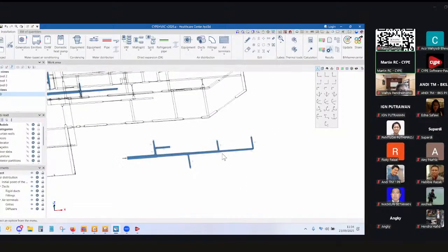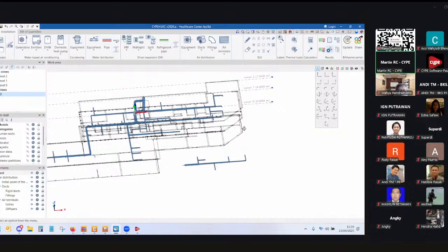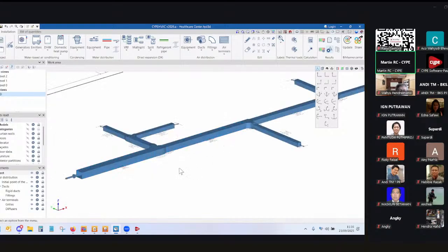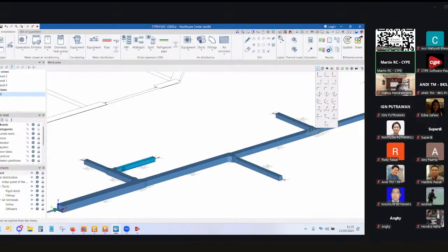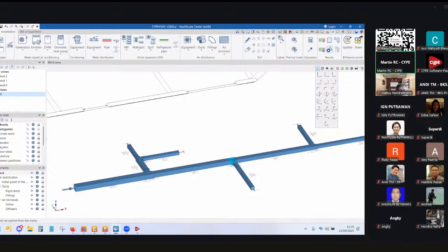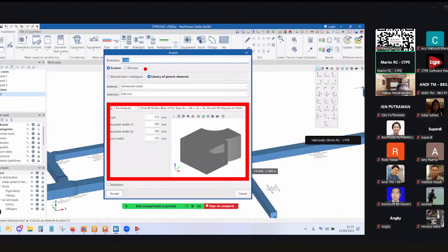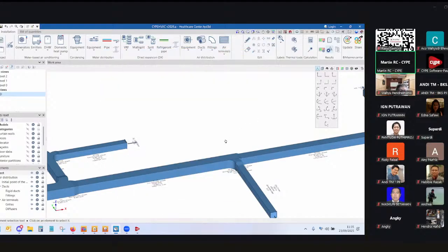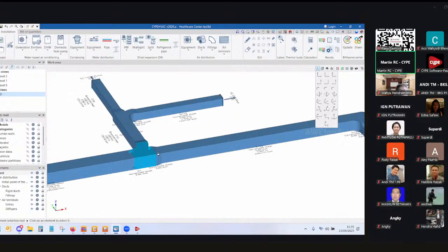If it's blue, it means I have properly connected all the elements in the installation. And see that we have an output where I have the automatic sizing of the different ducts in order to keep the installation working. And then I have the special fitting pieces that are automatically generated. In this case, generic elements means that we will be using ASHRAE methods to generate these, not only the branch, but also this special element. It's been automatically generated and listed, of course.